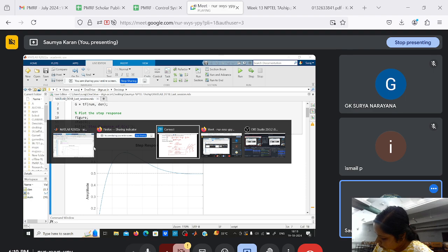So first step is to identify poles and zeros, right? Your poles are s is equal to 0, -2 and -5. Zeros, we don't have any zero, so it's none. Okay. Then what we do? We determine the asymptotes. What are the number of asymptotes? It's n minus m, which is 3 minus 0, which is 3.